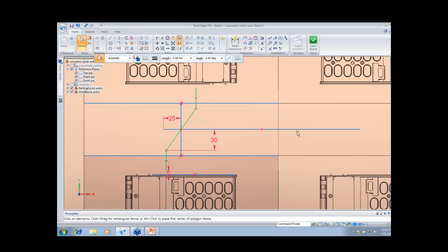So I'll grab the sketch and say I want to rotate it onto the other side. Looks good. I put this at the middle so that we have symmetry. Now you'll see all of them are linear elements, and these will act as injection channels.